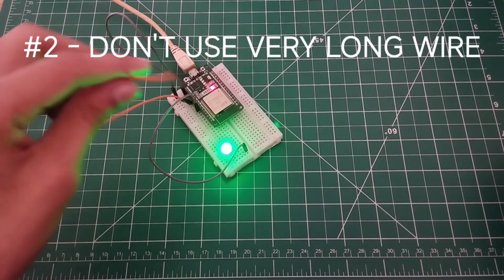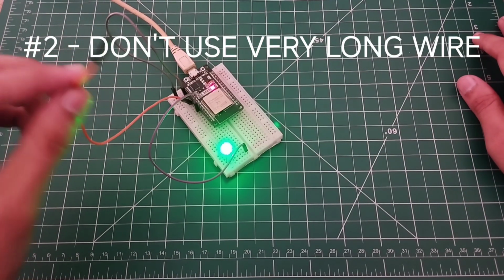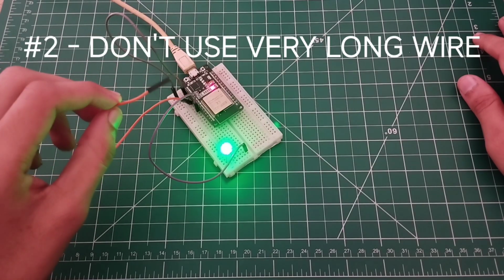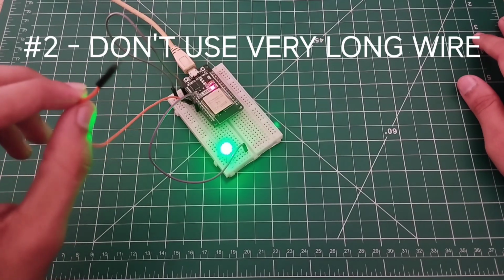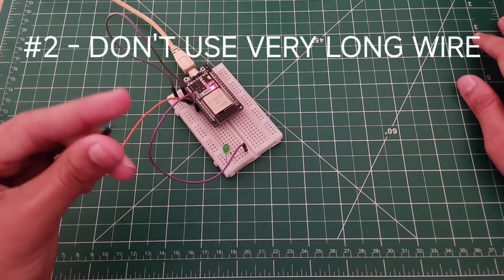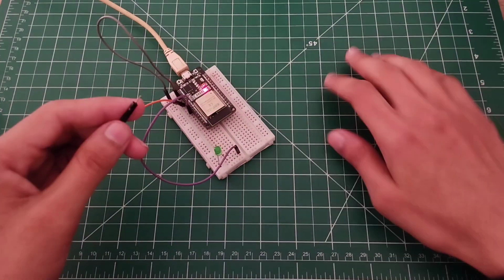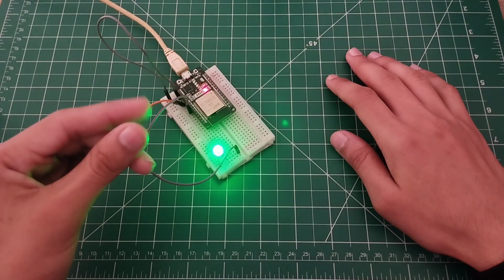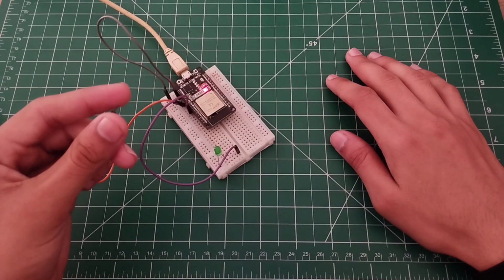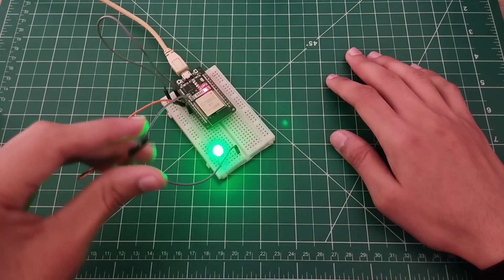The second mistake is that you should not connect a very long wire to the touch sensing pin on the ESP, because the touch sensing on the ESP32 is highly sensitive, and even a tiny change in the capacitance is detected by it. A very long wire behaves like an antenna, so it can obviously interfere with the surrounding environment and cause fluctuation in the values returned by the touchRead function. And the long wire also has its own capacitance, right? So even without touching it, the raw values returned by the touchRead function become lower than normal, so it might look like a false touch to the microcontroller.